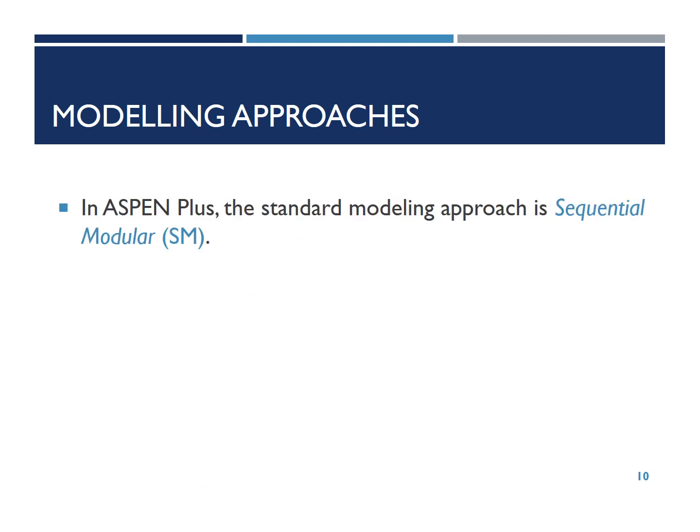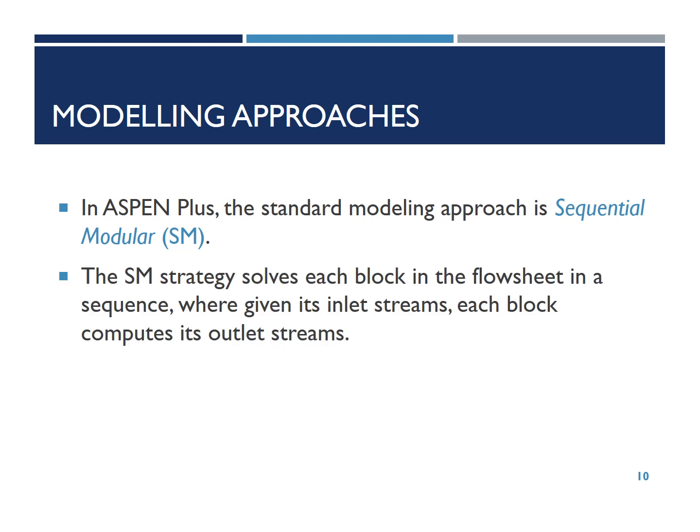In ASPEN Plus, the standard modeling approach is sequential modular, or SM. The SM strategy solves individual unit models or blocks in a sequence, where the output streams of a unit model are evaluated based on the input streams and design parameters.